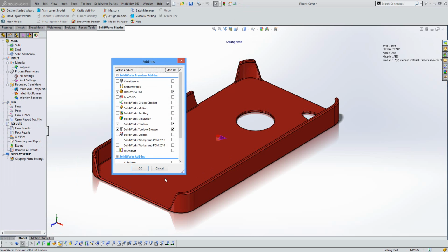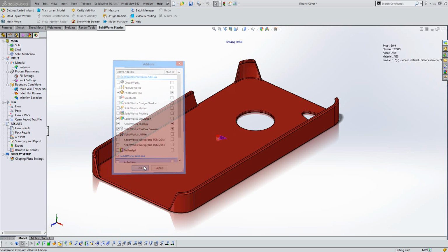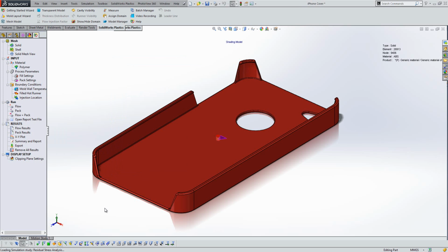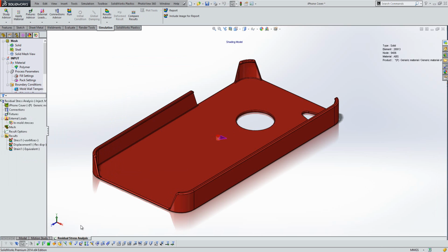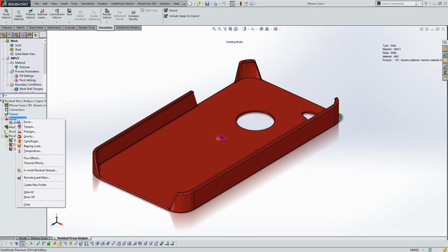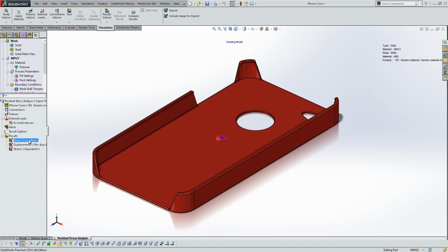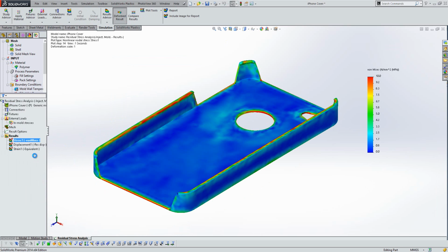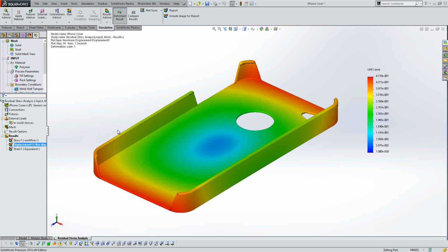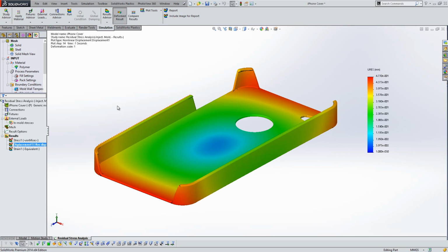So if we turn on simulation here, we've got a plot towards the bottom which is actually reading in those results. So in Nonlinear Analysis we can apply the residual in-mold stress as a load onto our component, and then that will run a study which will show us the residual stresses in the component, and also really useful is the displacement as well. So if you are looking at how your product deforms during cooling, we can now see that with the introduction of the new export options.